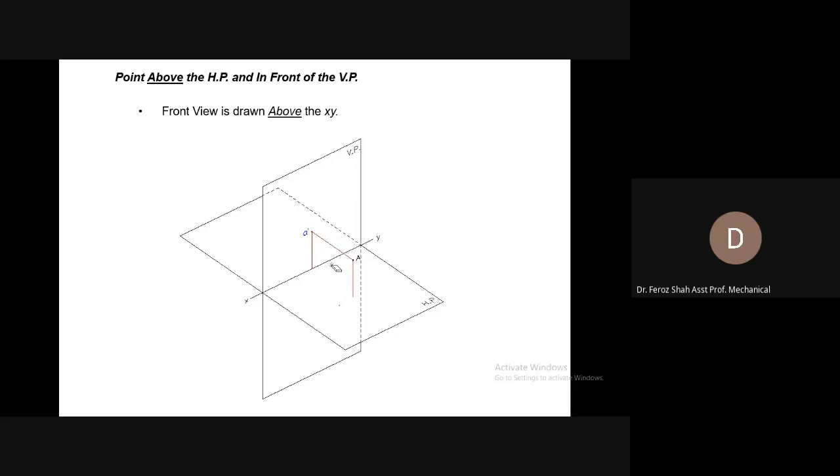So these two planes are used for references as well as for projections. The common line that these two planes form is called the XY reference line, because the same line can be used for referring to anything with respect to the horizontal plane, or X, and anything with respect to the vertical plane, or Y. That is why it is called the XY reference line.